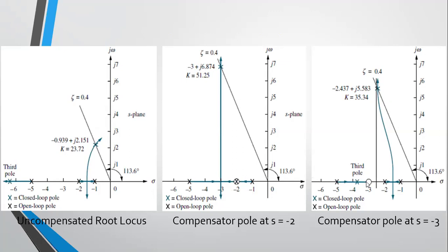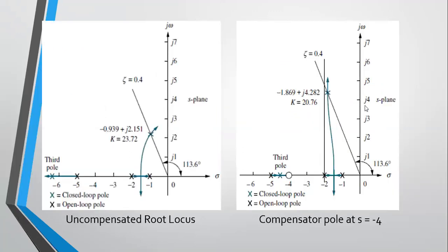Okay. Now again, in this case here, we are more interested in the dominant pole. So we'll have a pole along this branch here, of course, but we're going to look here because this is what causes a transient. We know it's when your poles have an imaginary part. This is where we get your transient response. This is where we get oscillation and specifications like peak time, settling time, or overshoot. So we see now when we have this 0 at -3 here, it is intersecting at this point. So we get a new operating point with a new real part and new imaginary part. Okay.